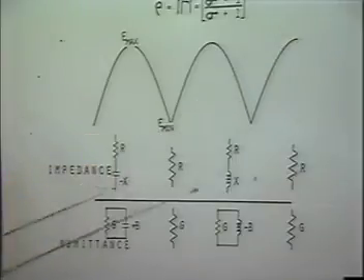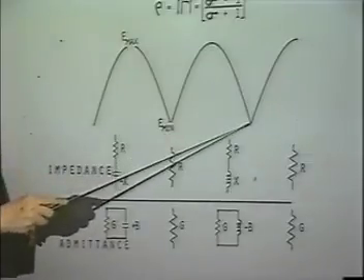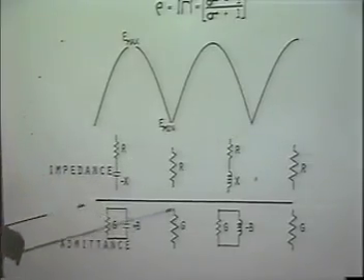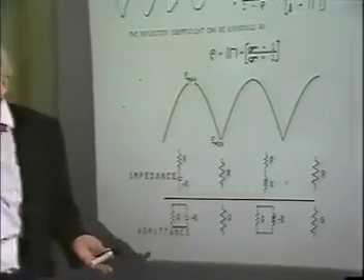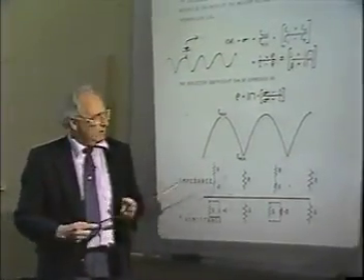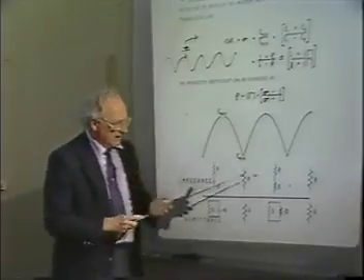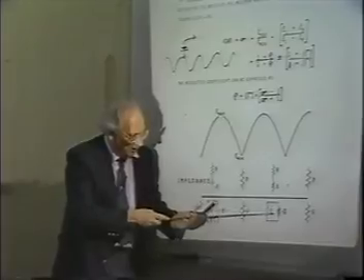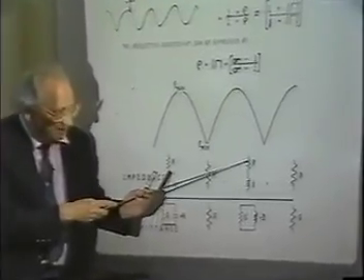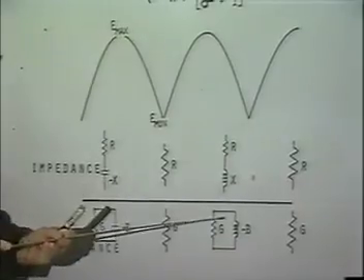Now, I just have an arbitrary transmission line drawn up here. I have this a very sharp minimum. Later on, you'll find that that minimum is less sharp as the VSWR, voltage standing wave pattern, gets smaller. To show that, first I'd like you to look at this, though. Here's the parallel equivalent of impedance. Impedance is a series problem, remember? Admittance is a shunt problem.